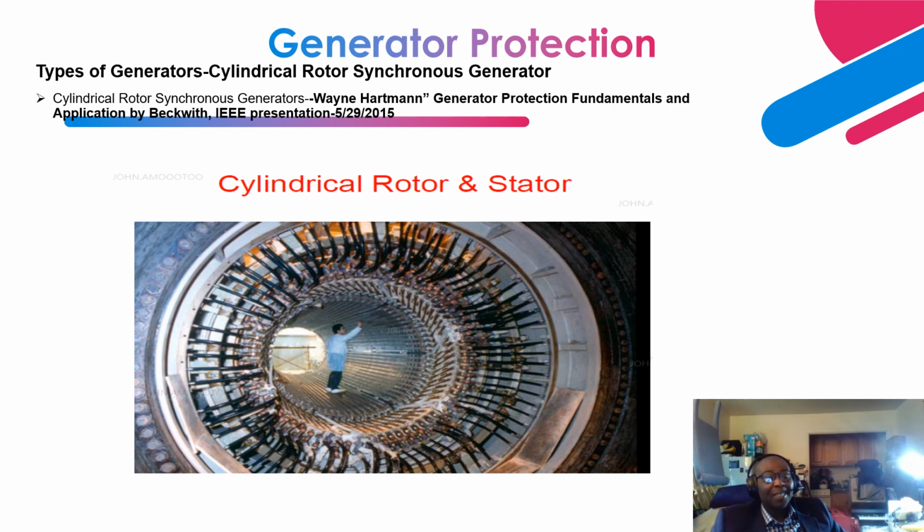So you have the generator engineer, or maybe the plant engineer, who has been trained how to do these inspections, moving from one end of the generator to the other end, inspecting each slot of the generator where the windings are located, and the end bell area where the end winding is, looking for heating and looking for damage to the core, the winding, and the insulation system.